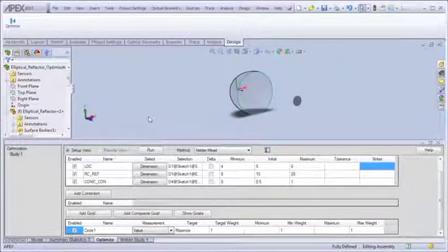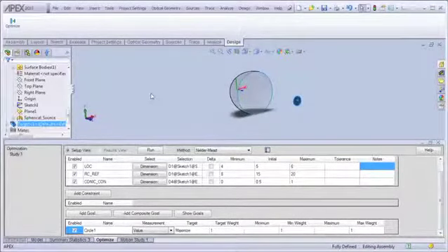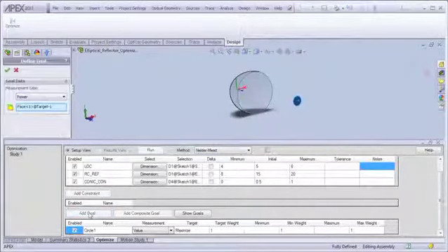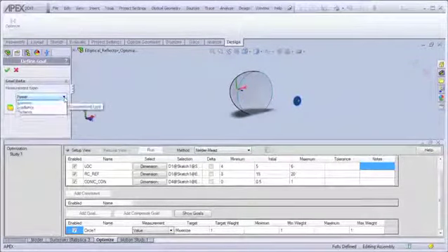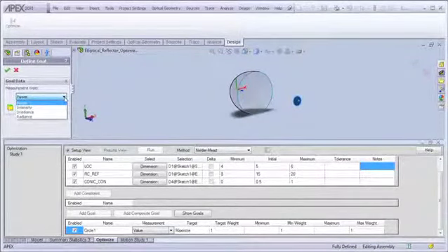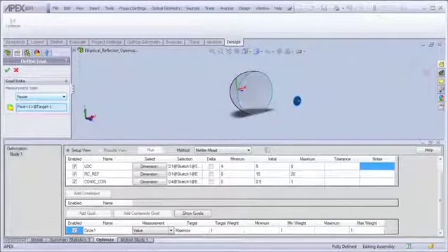Optimization goals are created in steps. In order to add a goal, you must first identify a target on which you want to place the goal. You then press the Add Goal button. That particular object is indicated in the measurement type box. You can choose from 4 different types of measurements: power, intensity, irradiance, or radiance. In this particular case, we're going to be optimizing or maximizing the amount of power on this particular detector plane.